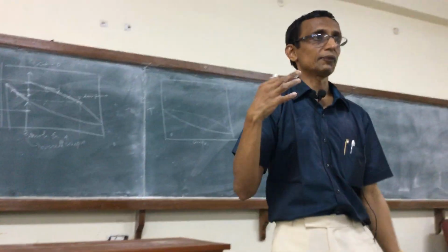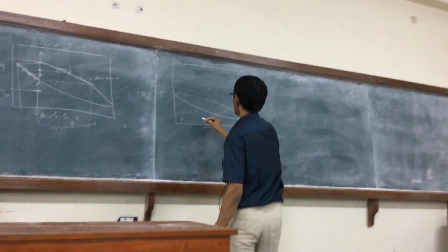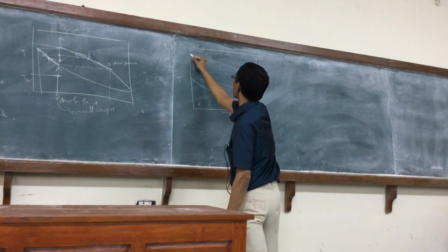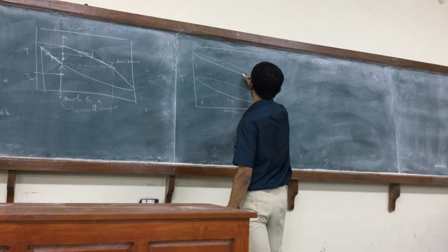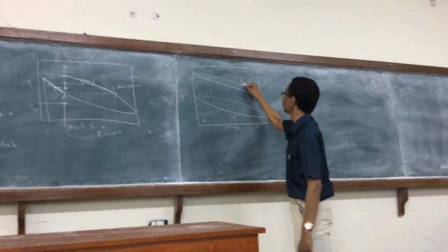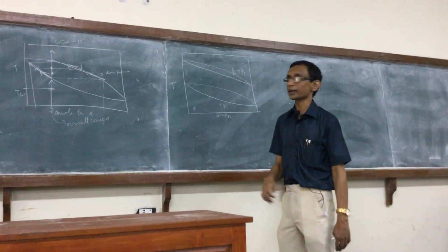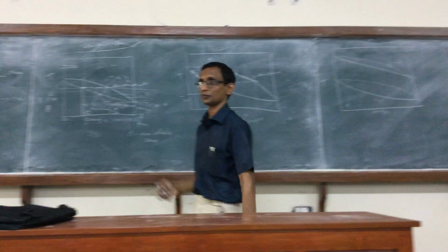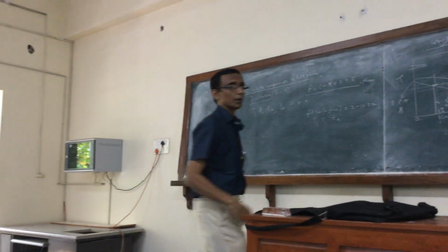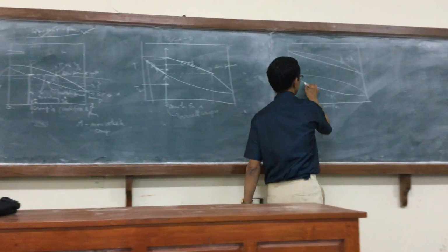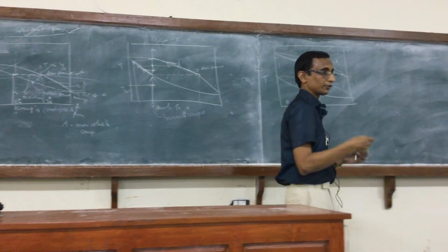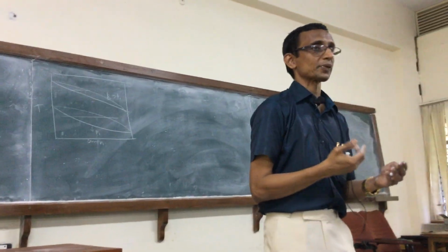The whole curve moves. So if this is at P1, the higher curve will be at a higher temperature, and also the region enclosed by the envelope becomes smaller and smaller. So P2 is greater than P1. What you can clearly see is that from the point of view of separation, it becomes more and more difficult to separate because the difference between the liquid and vapor phases is becoming smaller and smaller. That's what it means. The region enclosed by the envelope is shrinking.